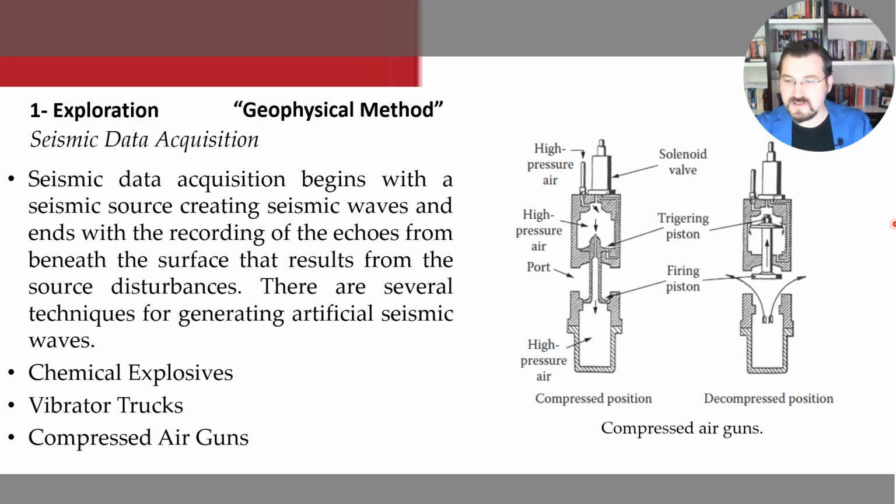The Earth's motion is detected by a transducer called the geophone on land and by a pressure detector called the hydrophone at sea, as we mentioned already. Hydrophones are pressure detectors that are sensitive to any kind of variation in pressure. Normally hydrophones are kept a few feet below the water surface in marine operations. Piezoelectric and magnetostriction types are common in hydrophone structure. The sensing element in piezoelectric crystals is barium titanate and lead zirconate, which are good piezoelectric materials used in hydrophones.